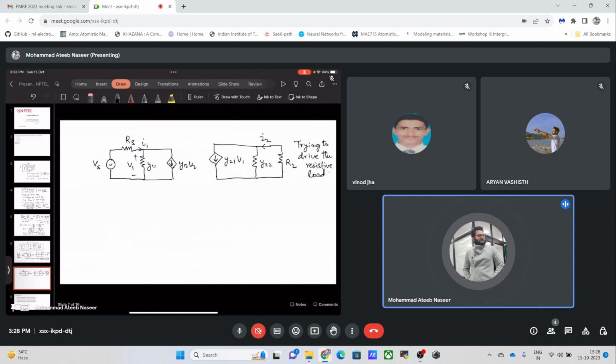So basically, till this point, we have been dealing in these resistances. It would be better if we skip this and go rather to the conductances. If we deal simply in the conductances, this Vs will become a current source, Vs times Gs, and Rs will become Gs. Y11 we keep as it is, since we are dealing in conductances.